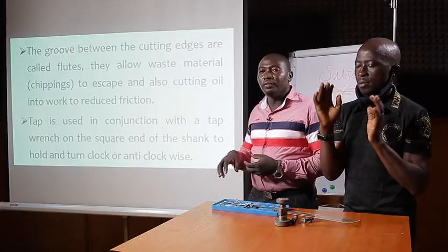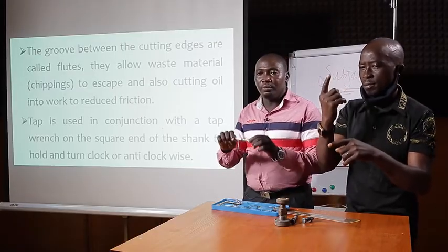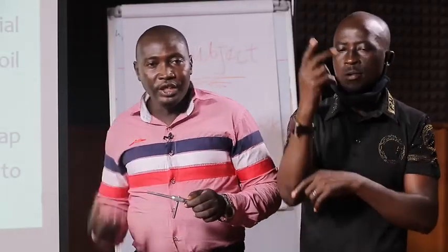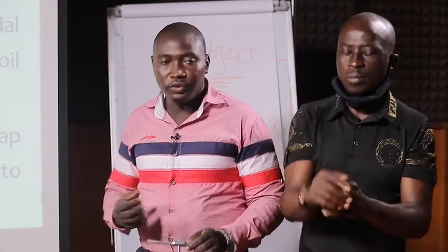By the time you run the first tap, you insert the second tap, as well as the third tap, to finish the hole or to finish the thread.